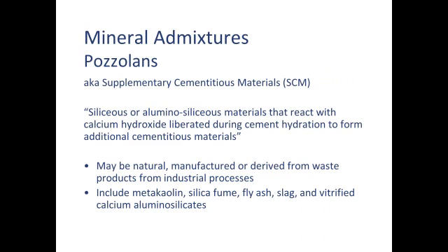The strength aspect is mainly done with pozzolans, and these are mineral admixtures, and they're also called supplementary cementitious materials. And there's a common definition that's thrown about. It's in the quotes, and I'm not going to read it because you can read it instead of me saying it. These are mineral admixtures that are put into the concrete, and they can be used in addition to your cement or partially to replace some of your cement to make your concrete better. I'm going to explain what they are, how they work, and the differences between them.